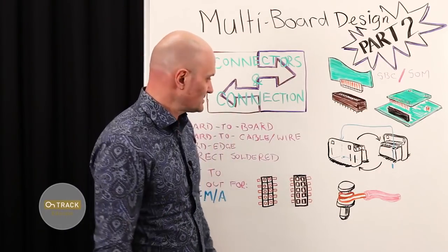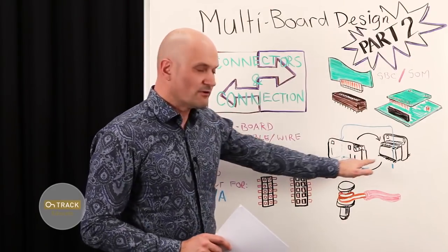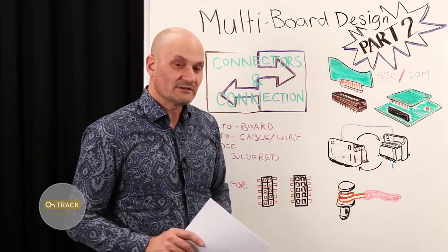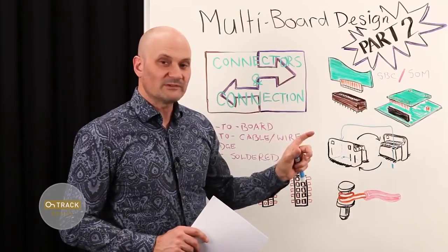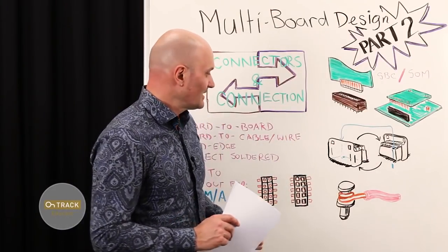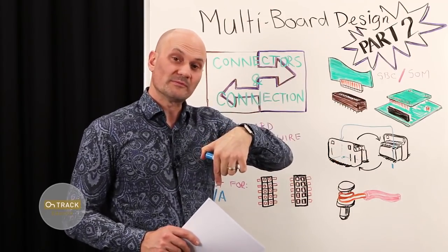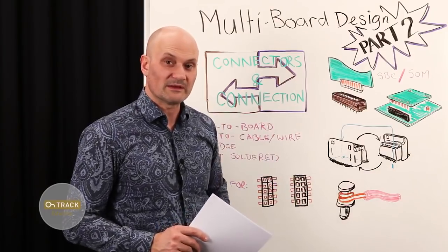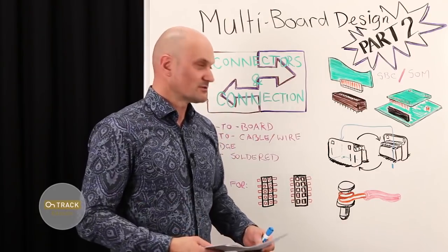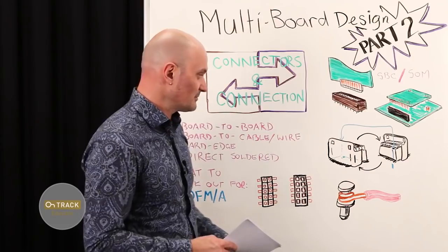you're going to have to enable it to allow those mirrored connections. Or the other way to do it is you create two footprints for the same library component, kind of like a variant, if you will, and you have the same schematic symbol but two footprints, and you can choose which footprint to place based on if it's mounted on the top of a board or if it's mounted on the bottom and mirrored, in which case you mirror the pad numbering or pad designators in your footprint to reflect the actual connectivity that's going to be in the final multi-board assembly.